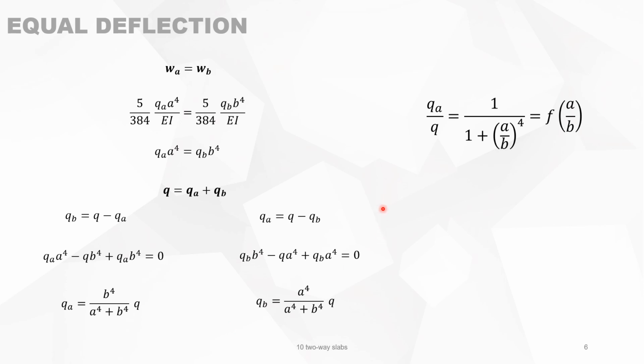In general, the load carried over in one direction A is only a function of the geometry of the slab. So in our case, for simply supported on all sides, it is this simple formula. You can now consider a cyclic permutation. It means you change A in B and B in A, and you have this formula, which is exactly the same as stated before.